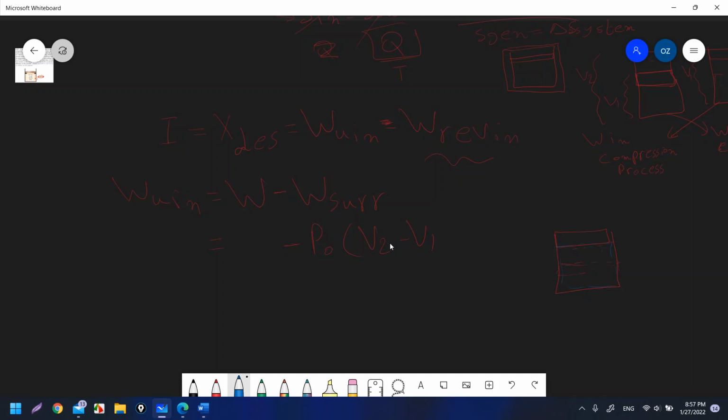After a compression, it will be this control volume. This will be my system. The system changes the boundary. So when there is a moving boundary, you can say there is a boundary work, W_b. That is the only work in the piston cylinder device that we can see now.